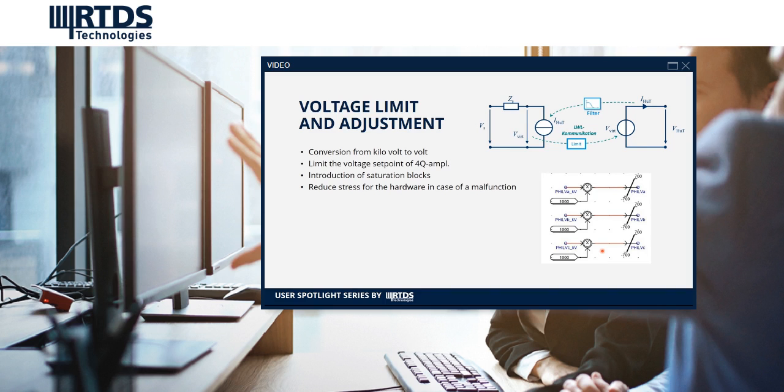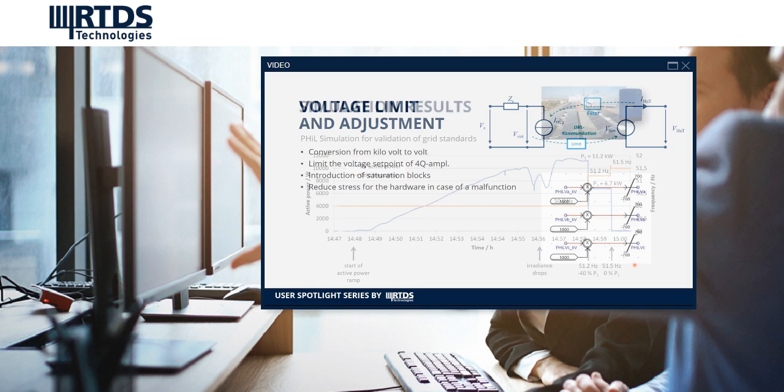And furthermore, I limited the voltage set point of the 4-quadrant amplifier to minus 700 to 700 volt by the introduction of saturation blocks to reduce the stress of the hardware in case there is some malfunction or some overshoot, so that there aren't voltages over 700 volt on the hardware.